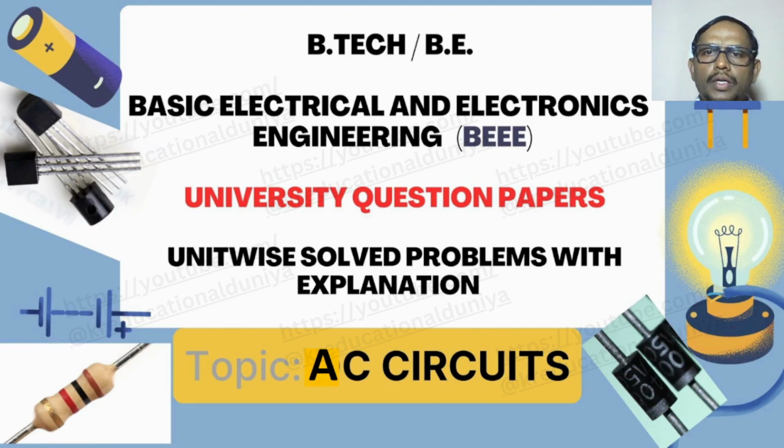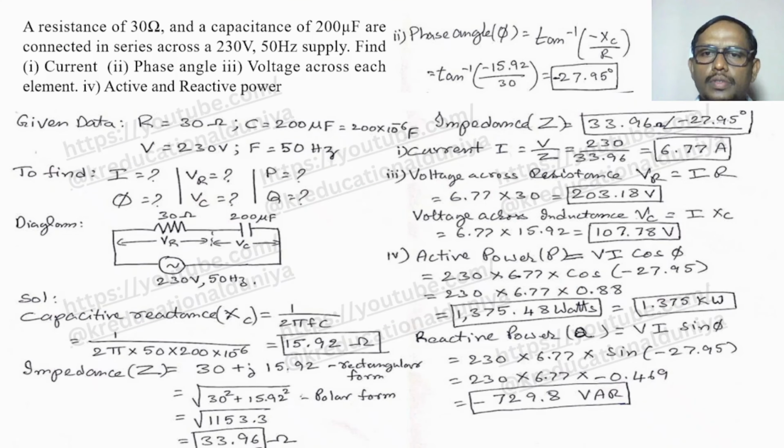In this part 2, we are going to see some of the problems in AC circuits. A resistance of 30 ohms and a capacitance of 200 microfarad are connected in series across a 230 volts, 50 Hz supply. Find number 1, current; number 2, phase angle; number 3, voltage across each element; number 4, active and reactive power.